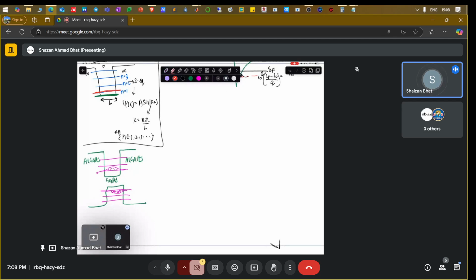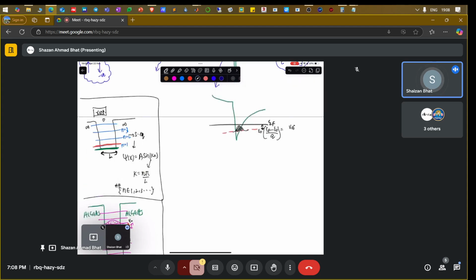But the mysterious thing is that the first energy level is not here, it's above it by a certain value. There is some energy difference between the first allowed value E0 and the bottom of the conduction band. That's very weird. A similar thing happens here when you solve the Schrodinger equation for this potential well. The first energy level, one would assume, would be here, but it's not. It's above the conduction band by some value. It's very small, 0.1 electron volt maybe, or 100 milli electron volt.